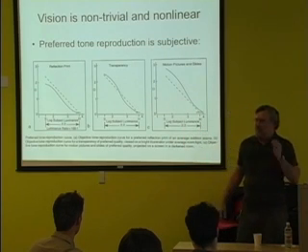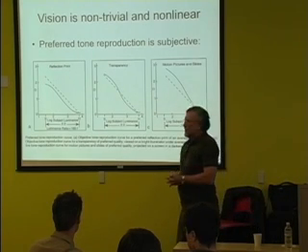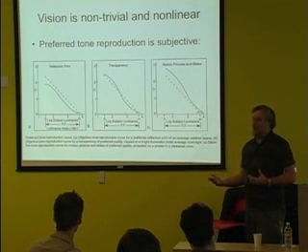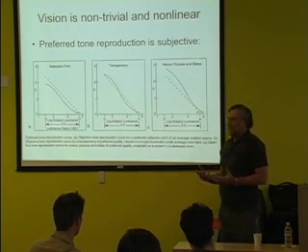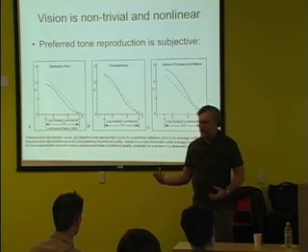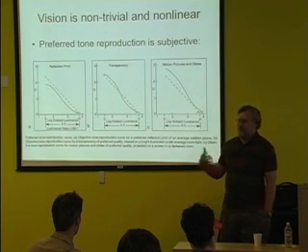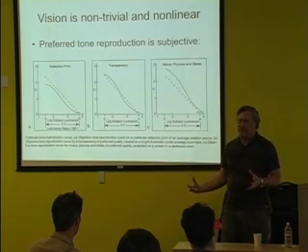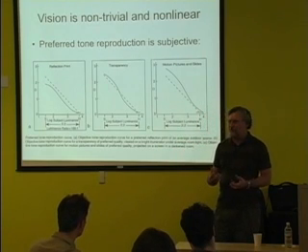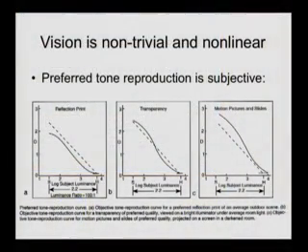Yeah, another question back here. Which one of these curves relates to an LCD or CRT monitor? And how do these curves relate to what the monitor does? That's another good question. It's part of that same thing. When I mentioned that in Photoshop you're working with gamma compressed intensities, that's because the whole notion of a gamma comes from the original behavior of cathode ray tube monitors, where the current coming off of a hot cathode responds nonlinearly to the voltage you put on it. That's the origin of the use of gamma in television representations that led to computer representations. But there are actually much better reasons to use a gamma compression curve, and I'll explain what all that is. The outline for the course mentioned that there's a whole module on gamma, because it's a hugely important topic and hugely misunderstood. I know that's not an answer exactly, it's just deferring the question to a later time.